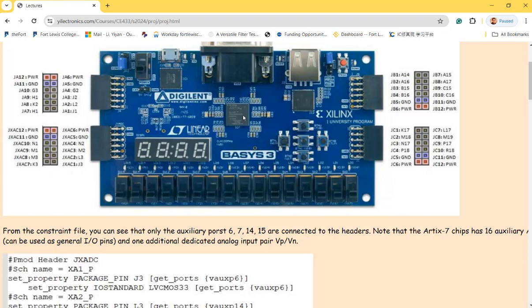So you can integrate more pins on it. And also it's taking less area because it's all underneath the package, so you are not taking space outside of the package of the chip, reducing the footprint of the chip on the board. Even though we don't need it to be that small on this FPGA board, what if a company wants to use this chip? They don't want to tape out their own ASICs, they just want to use an FPGA like what we are doing here, put a core on it, put the ADC, the peripherals and everything on it, and then just sell the FPGA as an integrated circuit.